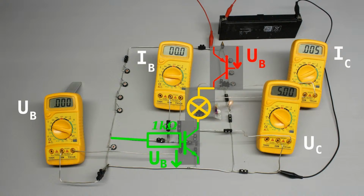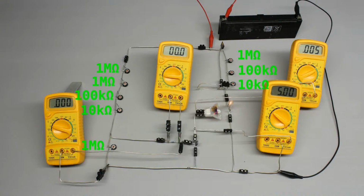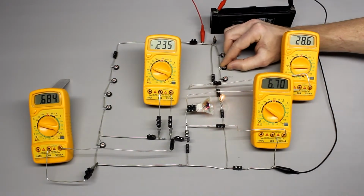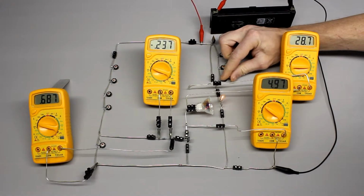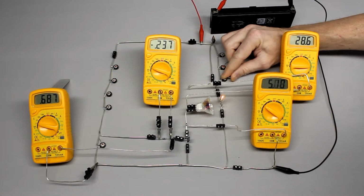Hence, the current running through the base pin is recorded indirectly by measuring the voltage drop at a 1 kΩ resistor. Potentiometers with a value of 1 megaohm, respectively 100 and 10 kΩ, are used to adjust the voltage drop at the base pins of the two transistors. Let's record the relation between voltage and current at the base pin with a constant voltage drop of 5 volts at the collector pin by using this arrangement.